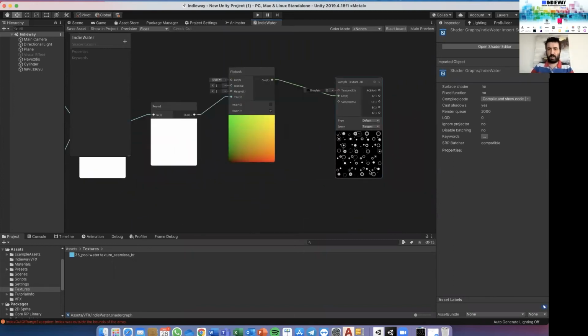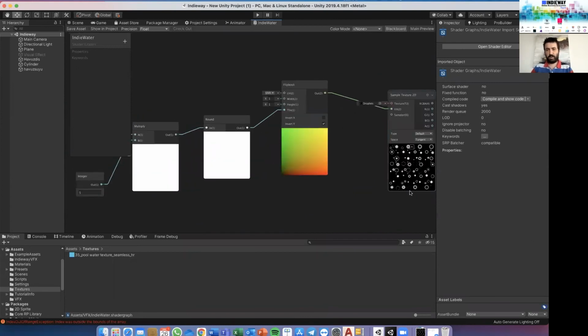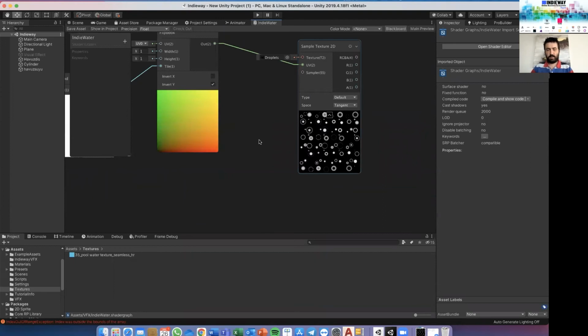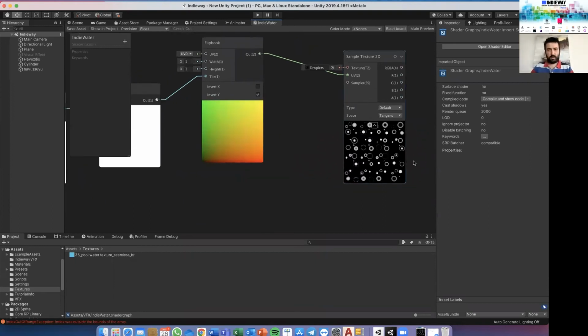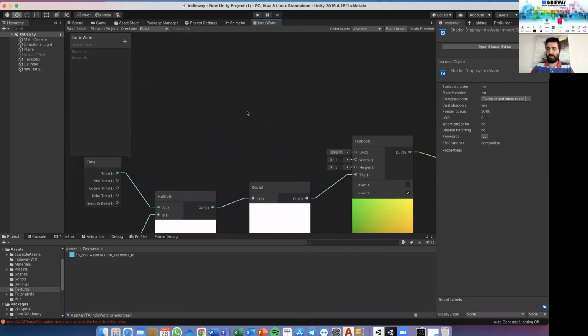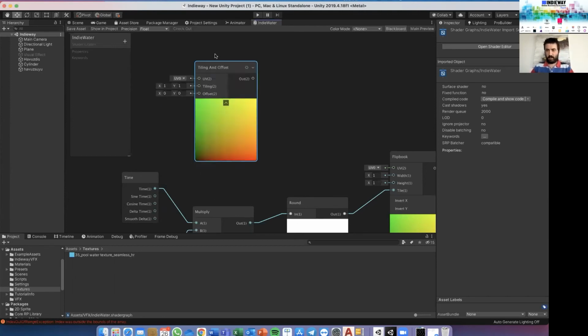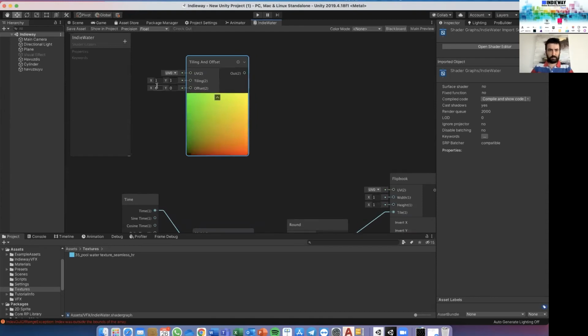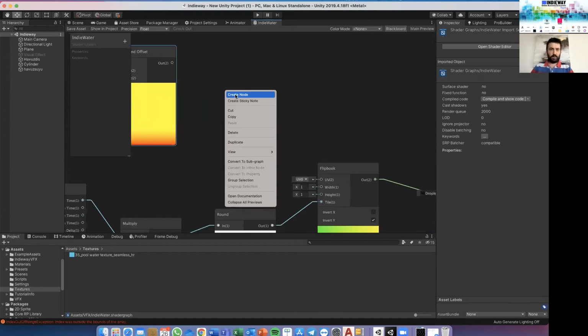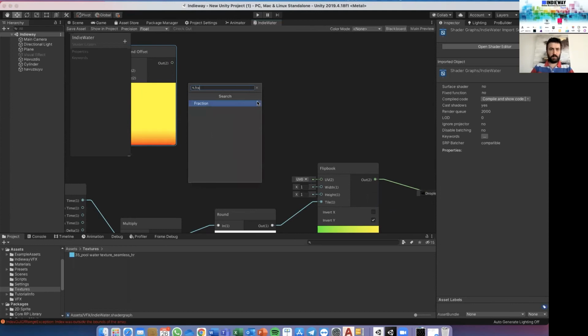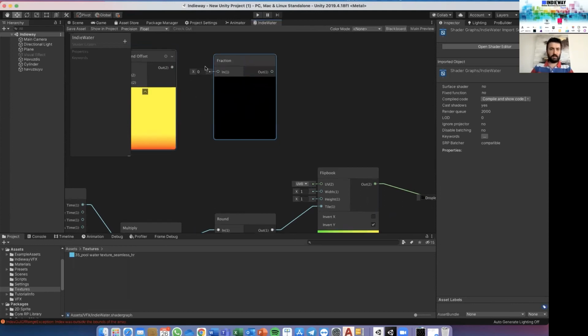at the upper part, in my sample texture, a 4x4 area is present. Before doing it, I will show you our 4x4 frame from the spreadsheet. Here I am again saying create node, and we have a node called tiling and offset. The tiling and offset node is typed as 4 for the X and Y, and here I am putting a fraction node.